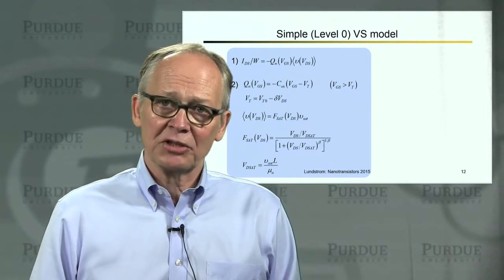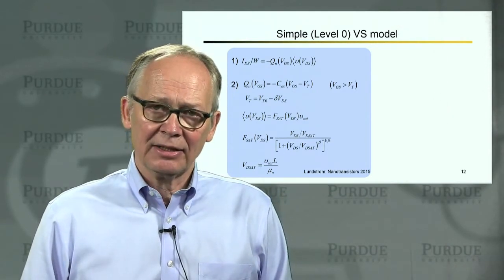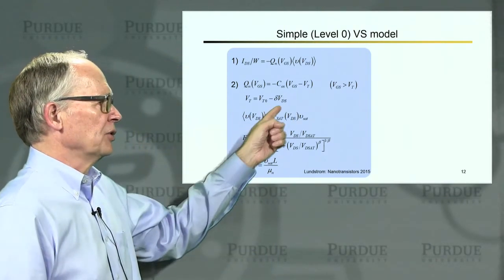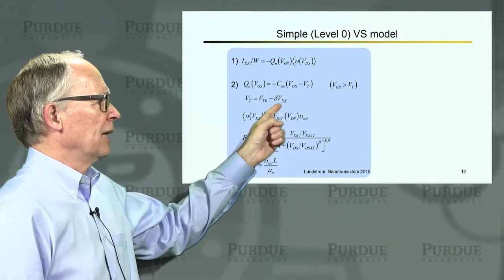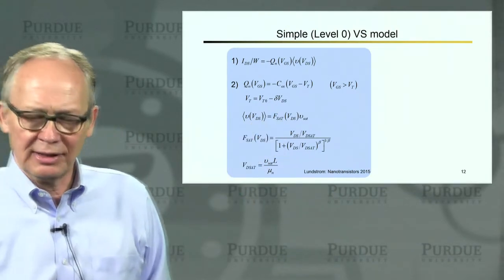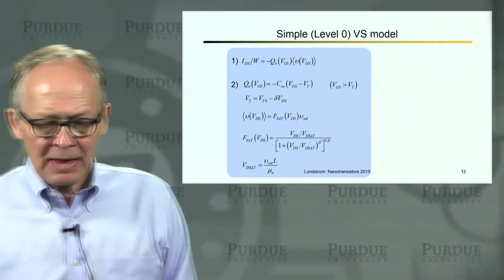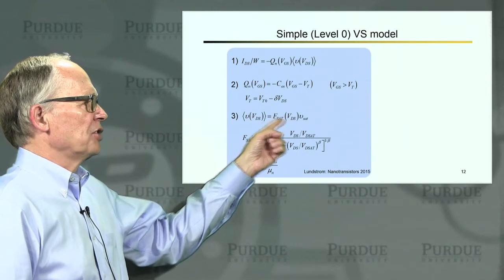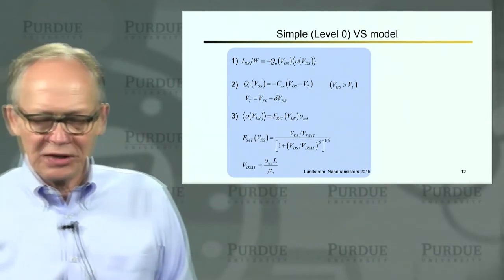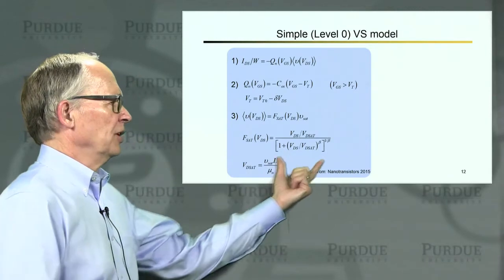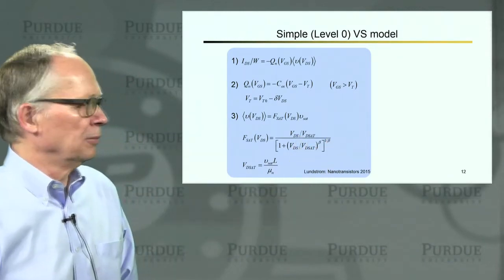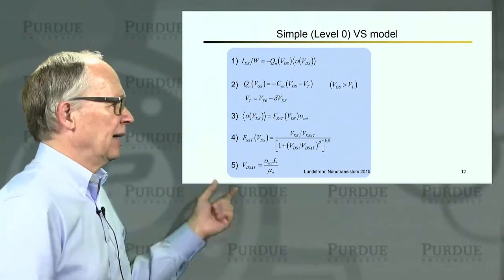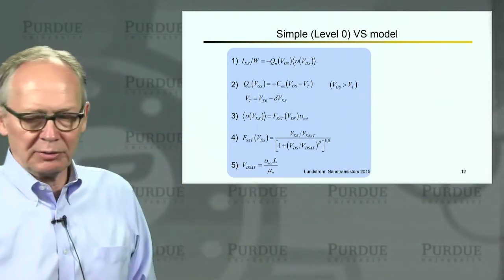We're going to develop a much more accurate and sophisticated treatment in the next unit, but we simply say that there is charge there above threshold, there is no charge below threshold, and we account for DIBL with a DIBL parameter delta. We modeled the transition from linear region to saturation region with this empirical drain saturation function. Here's the function that we developed. The parameter beta is an empirical parameter that we adjust to fit the data. And then we have the drain saturation voltage, which came out of our original model.